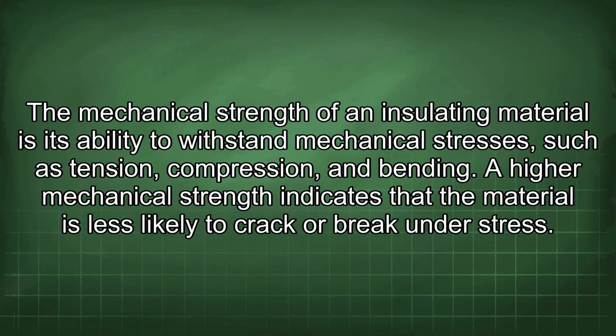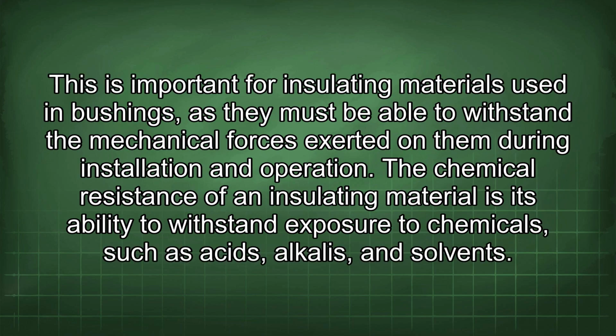The mechanical strength of an insulating material is its ability to withstand mechanical stresses such as tension, compression, and bending. A higher mechanical strength indicates that the material is less likely to crack or break under stress. This is important for insulating materials used in bushings, as they must be able to withstand the mechanical forces exerted on them during installation and operation.